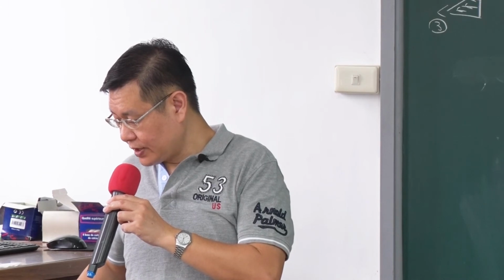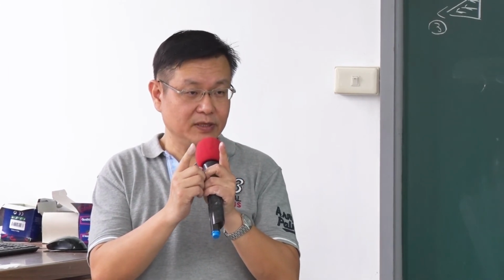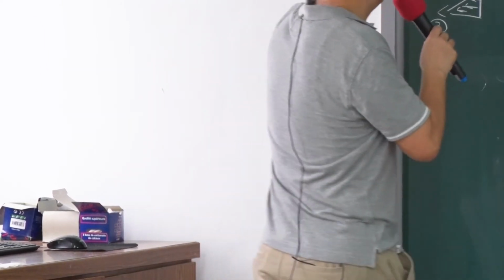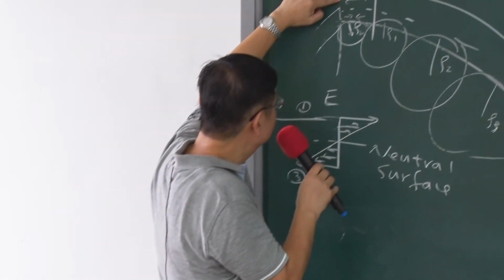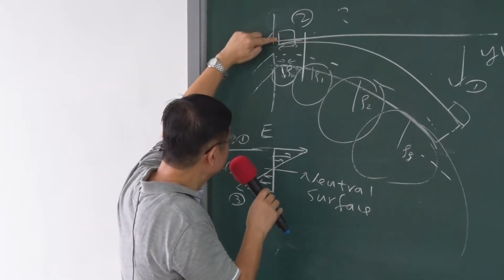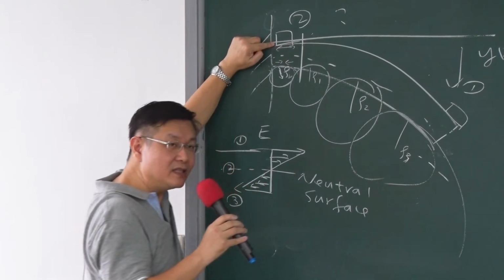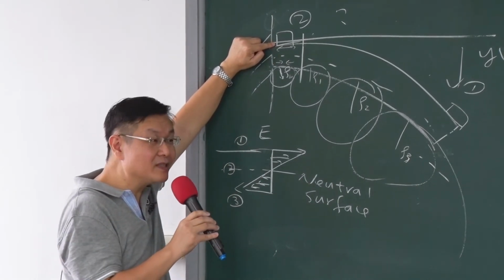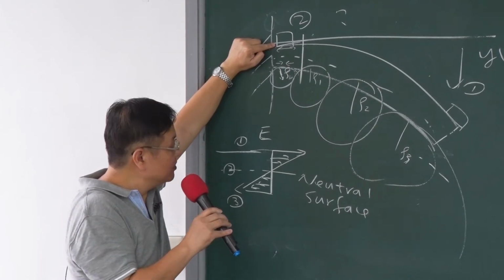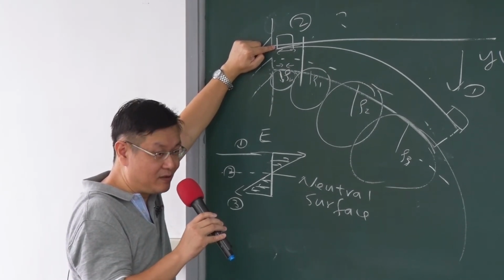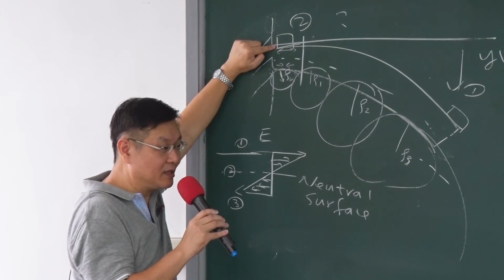Okay. Now we consider that our sensor is put on a portion of the surface. It's not positioned at one point, right? It's a certain length. So the sensor will cover not only one point, but a certain distance. So from this point to this point, the bending moment or the curvature will actually be different. That's why we need to average out the output signal, okay?